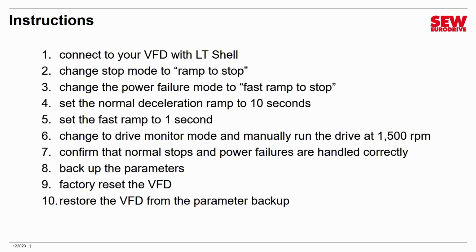Now, once you've run the drive and just confirmed that it works, I'd like you to take out your smartphone, fire up the stopwatch app, and I'd like you to test the normal stop deceleration, confirm that it's a full 10 seconds, and then test power failure mode. And I'll just give you a little hint how to test that. Just flip the off switch and see what the VFD does. See if you get that fast deceleration or not.